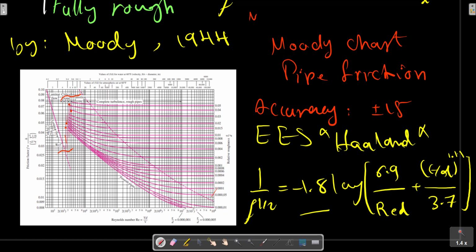For no reliable friction factor, the range, let me write, Reynolds number between 2000 and 4000. Notice that the roughness curves are nearly horizontal in the fully rough regime to the right of the dashed line. From tests with commercial pipe, recommended values for average wall roughness are listed in Table 6.1 in the reference, Pipe flow, fluid mechanics.